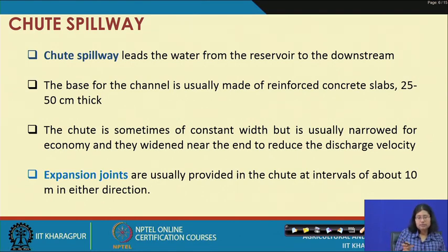Now, for designing of Chute spillway, we also need expansion joints, which are usually provided in the chute at an interval of about 10 meter in either direction.